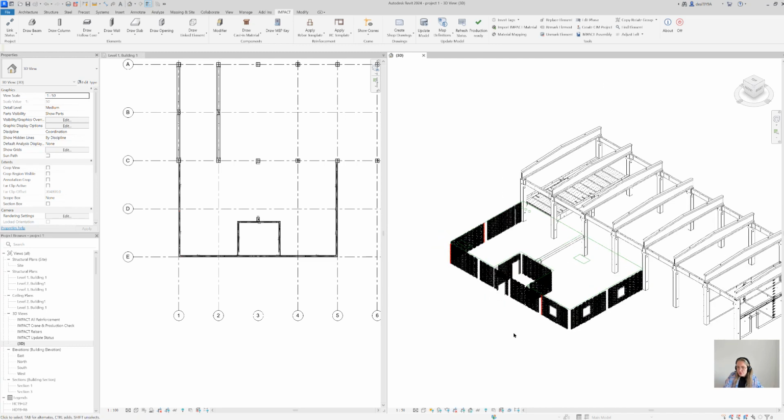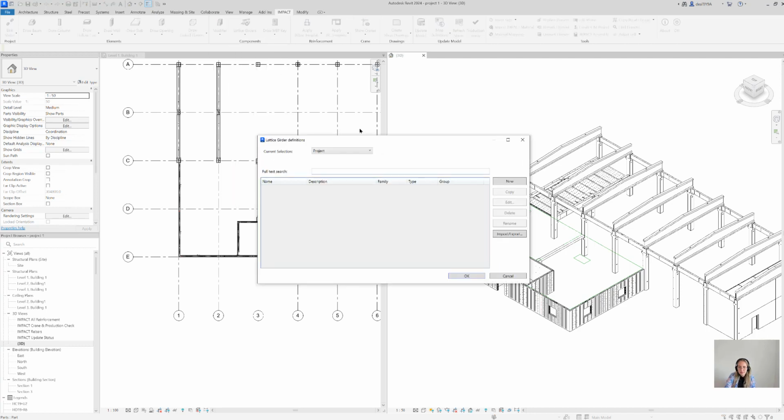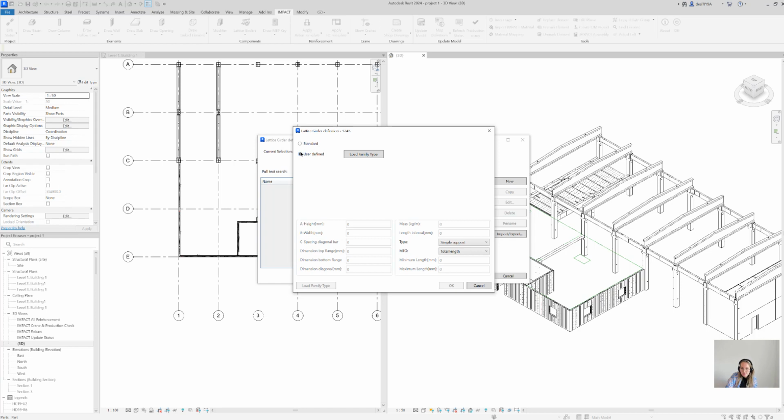The last thing I want to mention when doing this double wall part is that we have actually opened for user-defined lattice girders. If you go into this lattice girders, here is where we define components, and say you want to make a new lattice girder. You have the possibility to say user defined, and you can load your own family. Impact is almost all around the world now.